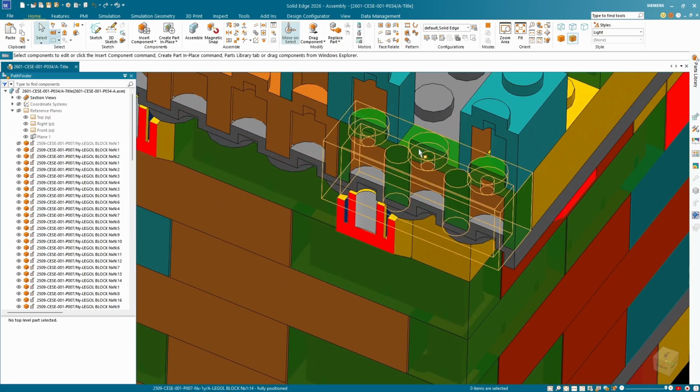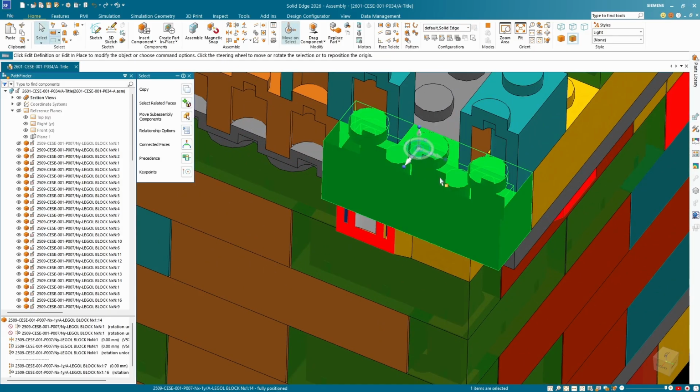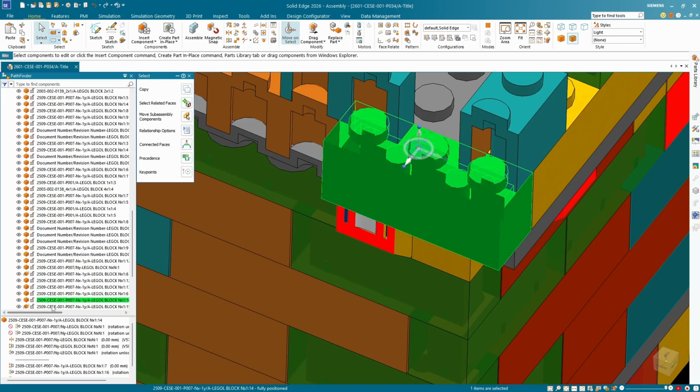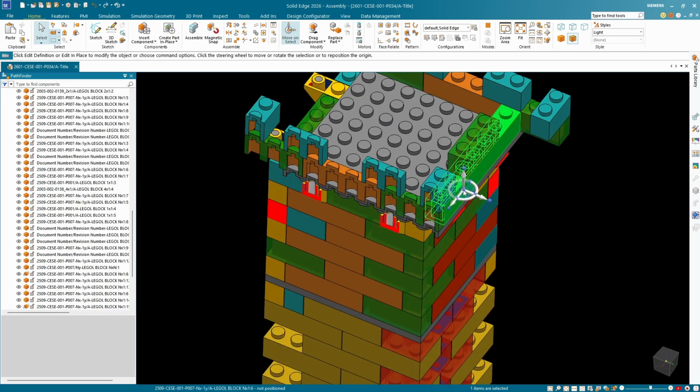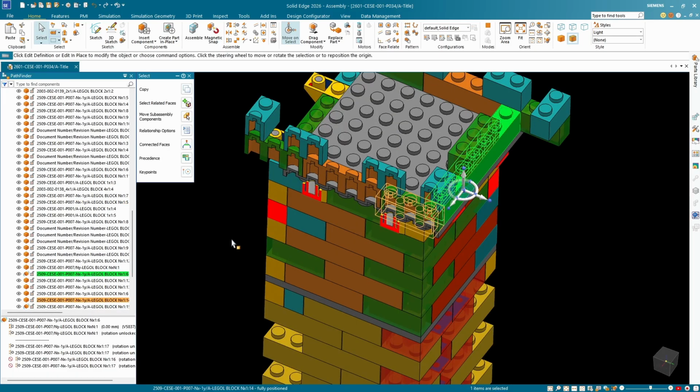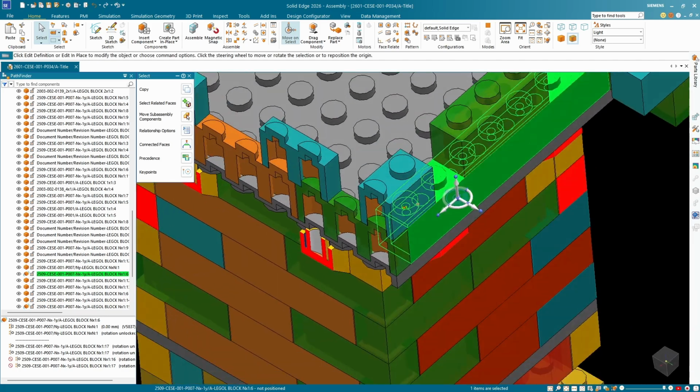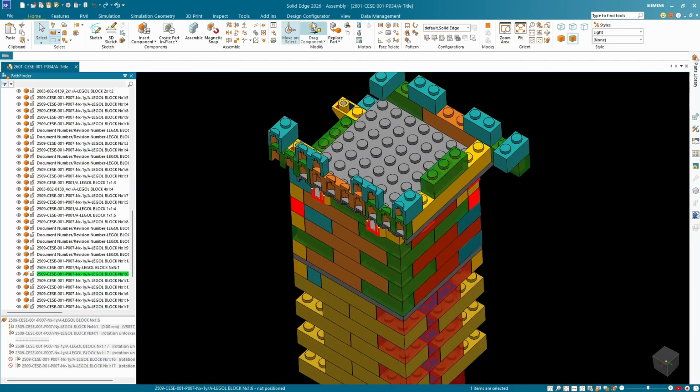Let me just right click. I'll click on that block and choose scroll to. That is fully constrained. That's okay. And our yellow block isn't fully constrained. So let's just investigate how our yellow block is free to move.